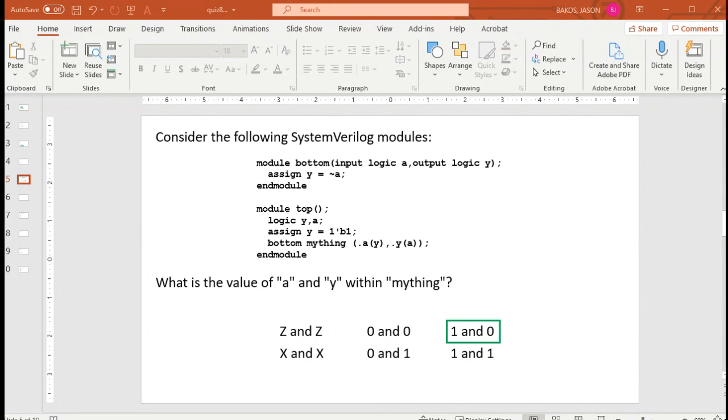That looks like a test harness, judging by the fact that it doesn't have any top level inputs or outputs. Normally, your top level module in Verilog would have inputs and outputs that would map directly to the pins of the chip. And then you'd connect those from the outside of the chip, the outside world, from the circuit board. But yeah, this one is confusing because the idea is that A and Y are swapped because of the way the port map is done here.